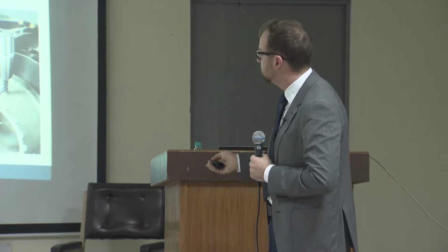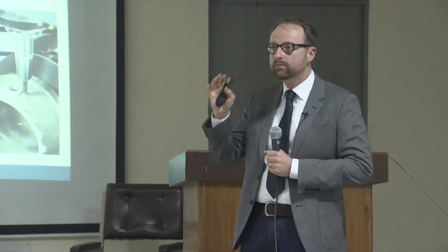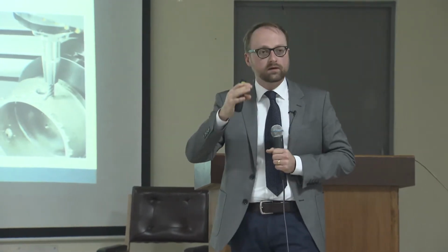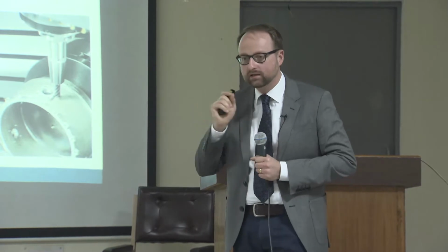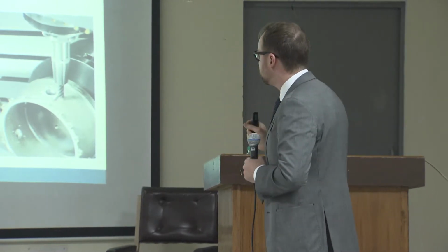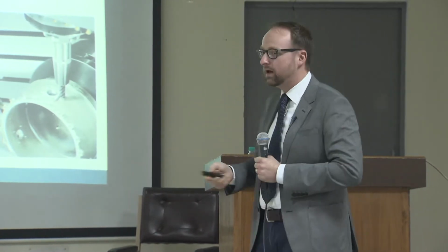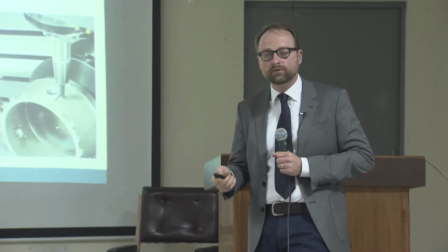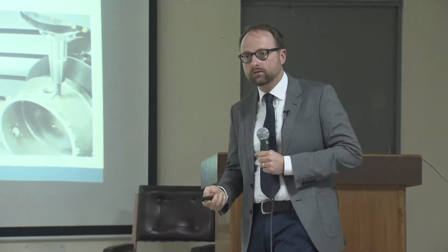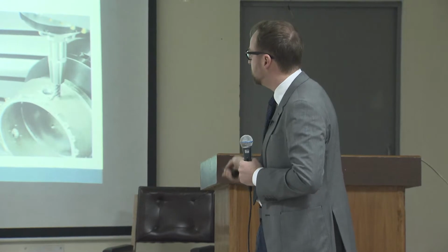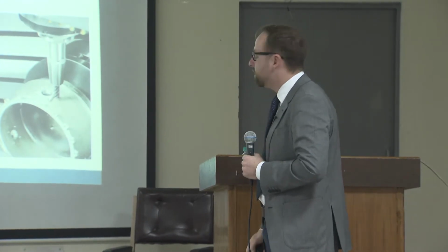Another one is actually, in many cases, you will need limited machining post-processing of these parts, which is why it's a near net shape operation and not a completely net shape operation. And therefore, when you have to do a little bit of machining afterwards anyway, it makes sense to combine additive and subtractive into one machine.